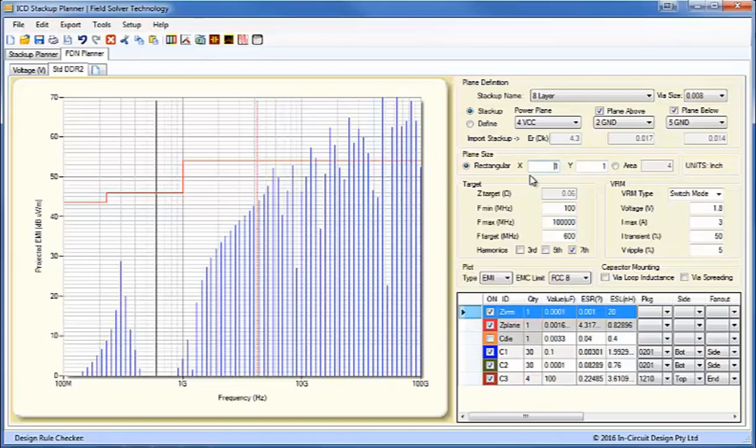the radiated emission. So it's really a combination of the stack up, adding planar capacitance as much as possible, and reducing the area of the planes, or shifting the resonance of the planes so that we're not on the harmonic frequencies of the fundamental.